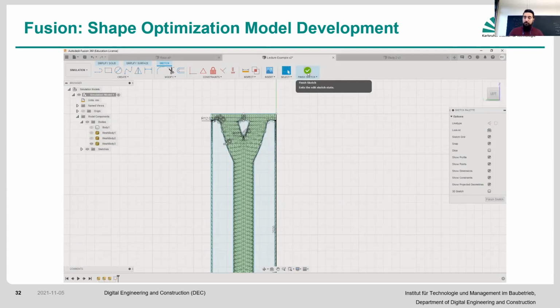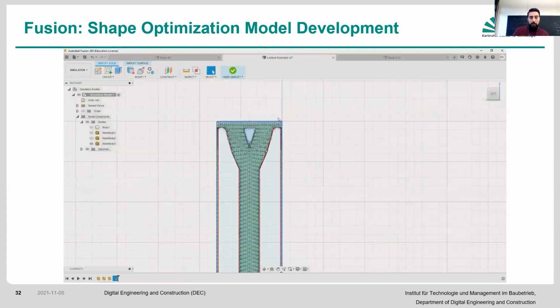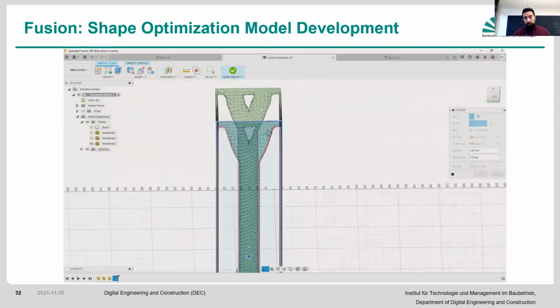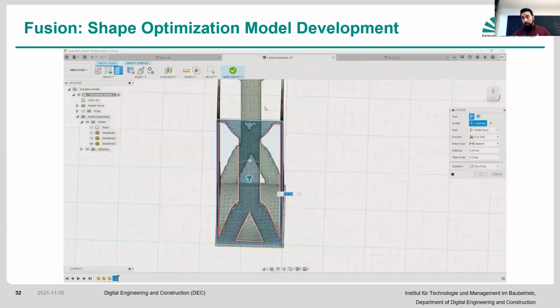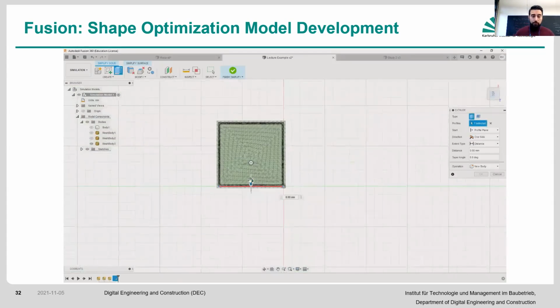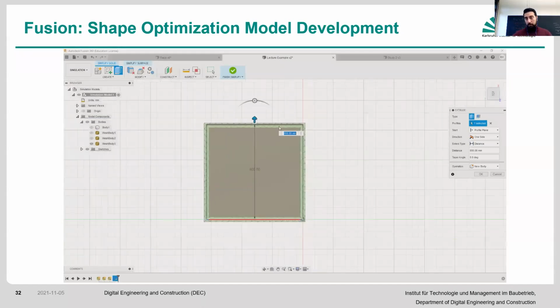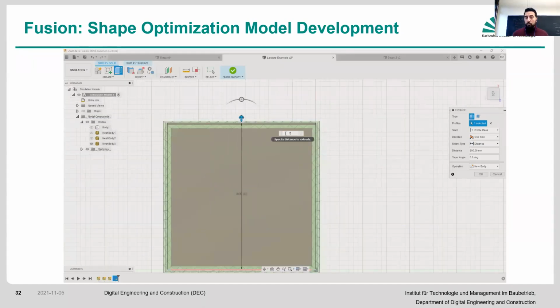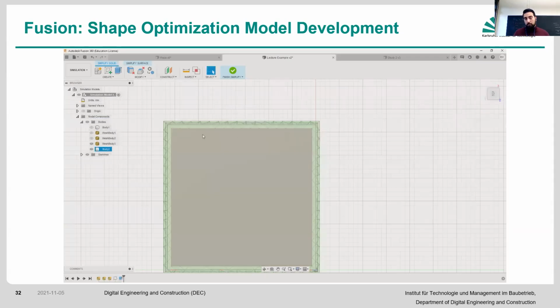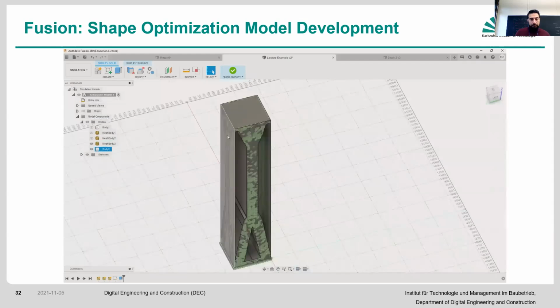And then once you extrude it, you would be able to basically capitalize on the actual finished structure. So you go there, you click on it, you go to extrude, and then it gives you how much you want to extrude. So if you go to the top, it basically gives you the direction. Direction is typically orthogonal to whatever surface it is that you want to extrude. So how much do you want to extrude? You want to extrude exactly the 790. That is the dimension of one of the sides of your square, right? So now it's extruded that, and it goes there.